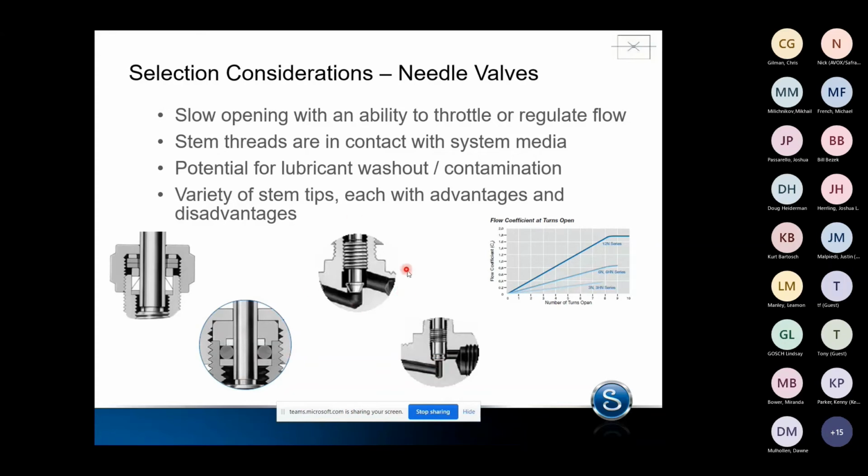So when we're looking at a valve, after we decide what the flow coefficient is, and we'll talk about that calculation in a little while, after we figure out what that flow coefficient is, we're able to then identify which valve is appropriate based on published literature. So either flow curves or other valve detail that tells us this valve is going to be enough to be able to get that flow through the valve.